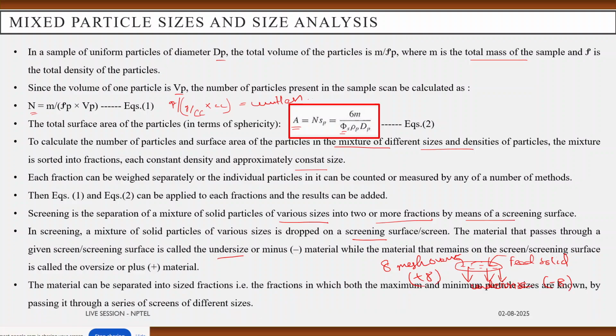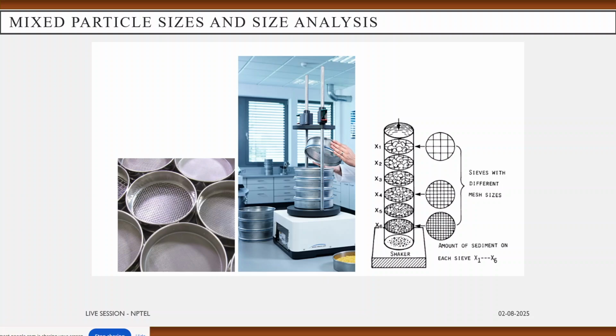The material can be separated into fractions based upon size, fractions in which both the maximum and minimum particle sizes are known, by passing it through a series of screens of different sizes. You can see in this visual demonstration how the screens are stacked one upon another for the size analysis.